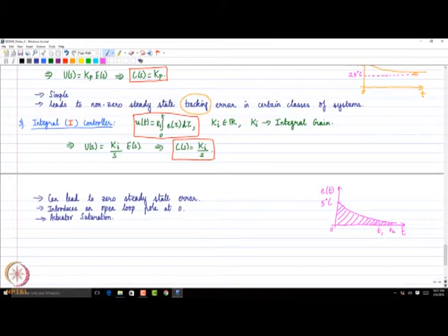For example, in this air conditioner, what is the actuator I may use? I will be using a compressor based cooling system. Let's say I have a certain capacity for the compressor and the fan assembly. And I keep on calculating this control input even as the temperature error gets closer and closer to 0, there may be a point where I have a saturation in the control input. I may ask for, let's say, x liters per minute, but the capacity of the actuator may be less than x liters per minute.